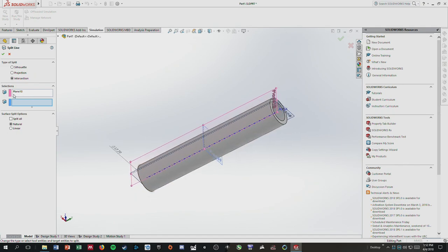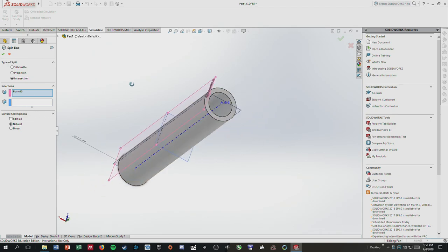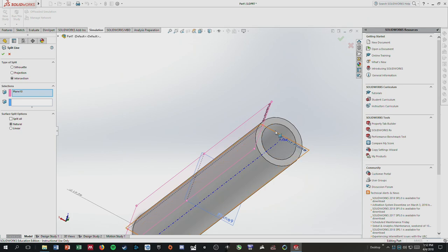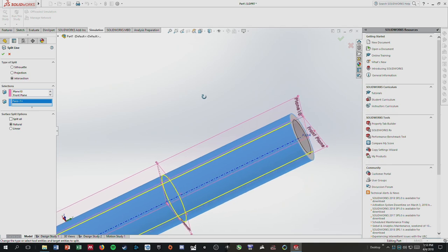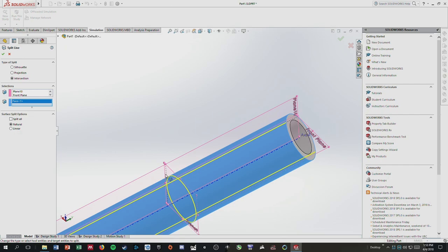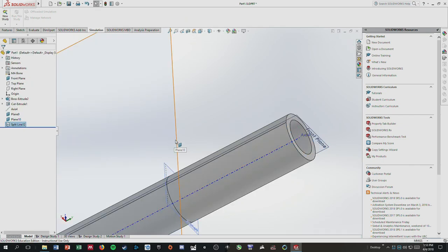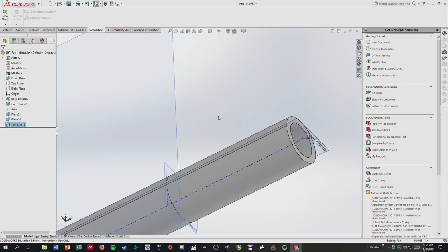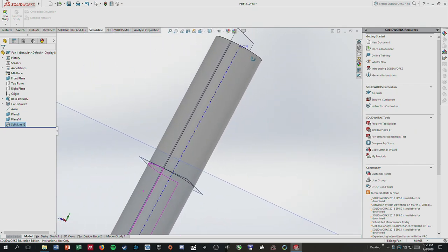When you're selecting the planes, you want to make sure you're on the purple, or pink, box, and select all of the planes that are used. There are 3 planes. Then we're going to select the blue box and click on the outer surface of our model. That should allow it to create the split lines you can see in yellow. Make sure that the intersection option is selected and then click OK. You can see the black lines that split the outer surface into quadrants have been created.